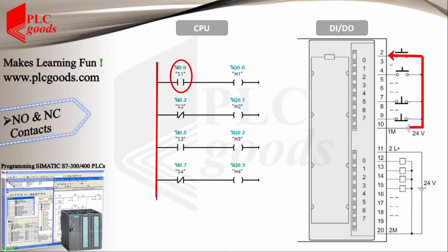The important point is that the state of this contact is changed based on the state of its digital input address, which works based on the voltage level at its input terminal, not based on the type of push button.